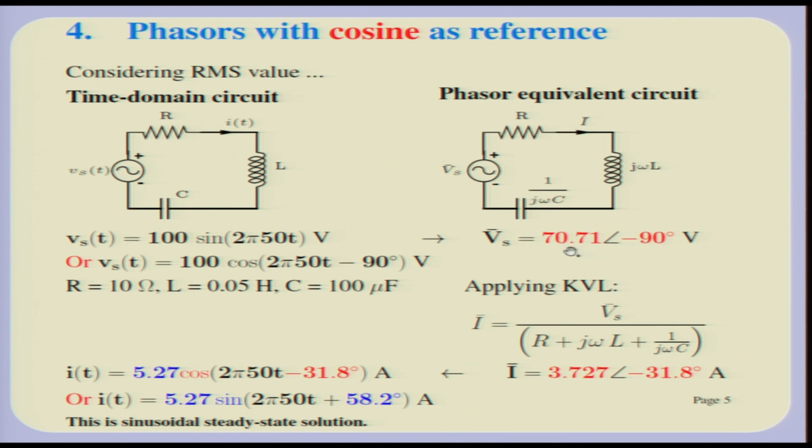Where V is defined by the phasor convention to represent the sinusoidal function there, and I is also a phasor, using the RMS value. So, if you take the multiplication of these two phasors, that is V into I conjugate, I conjugate means you have to put a minus sign on the angle, and then take the product, and it turns out that this is equal to the average power plus j into the reactive power as defined before. So, that is a very interesting thing.